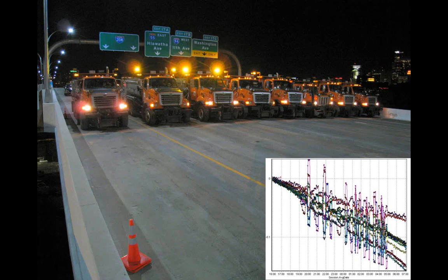Here you see an example of data that was obtained during a load test performed on the bridge. As you can see, a lot of trucks were needed to properly load the bridge, and on the bottom you can see the response to temperature, which is the general trend, and the jumps correspond to different load scenarios that were carried out on the bridge. Again, this was to check if the response would match the original design of the bridge.